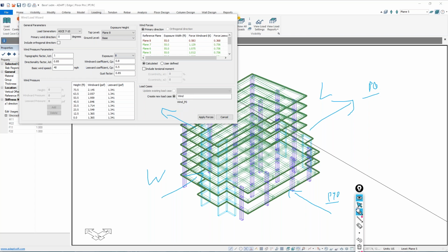If I wanted this to be reversed, and by the way, in the Y direction, this would be windward side, leeward side. If I wanted to reverse that, maybe I want this to be the windward side and the leeward side, now the entry for the load would actually be 270 degrees, and in the other direction, this would actually be 180. Now, as a user, if you did that, you would be managing 4 load cases, or more, depending on whether you're considering eccentricity. Or you could just do plus minus in the combinations, depending on how you want to achieve the loads.